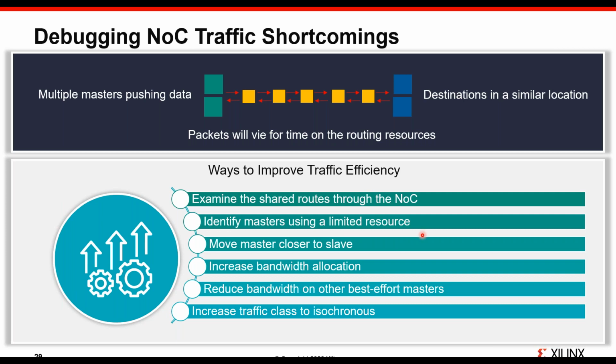So again, yes, there's some very high-speed lanes that are through this, but at most there's 4 on the lower horizontal NoC, and versus 2 on the upper NoC, and the verticals. There's only 2 paths in there. So yeah, they're fast. They can move copious amounts of data really fast, really hard, but if you're trying to put everything into the same channel, that can be problems.